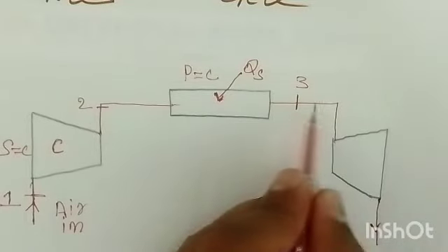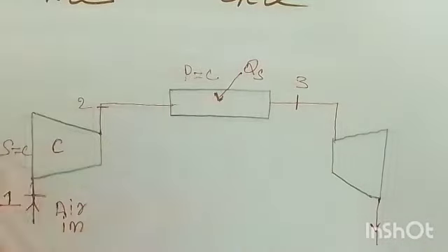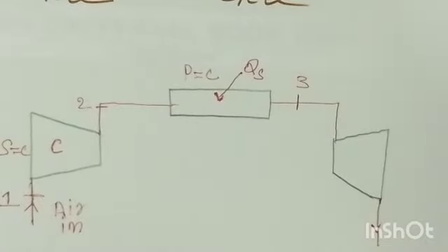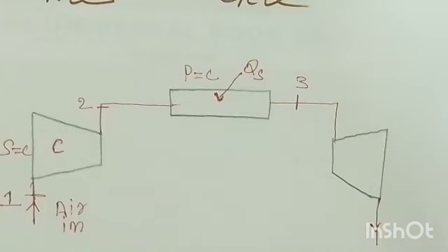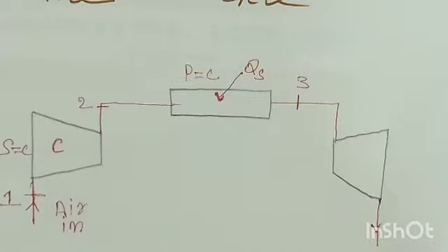Further, the hot gases will enter into the turbine. The turbine has a shaft, and blades are mounted on the shaft. The hot gas is not a normal gas; its pressure is maximum and its temperature is maximum. So when this high pressure, high temperature gas strikes the turbine blade, a thrust is created. Because of that pressure, the blade starts, meaning the shaft starts spinning, and because of that spinning of the shaft, work is developed.